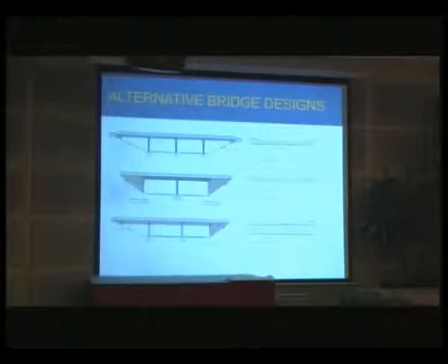Bridge 2 is 2-span, as you can see. It's 32 meters long. And this one's simply supported. So whereas Bridge 1 is a continuous deck, Bridge 2 we've assumed to be simply supported. It's got closed-end cantilever abutments with wing walls and intermediate wall pier.